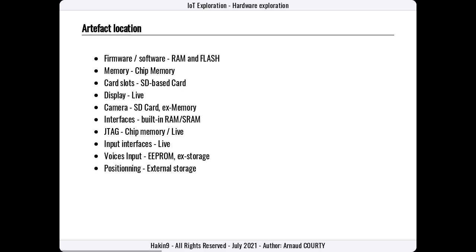From this methodology, these kinds of artifacts can be retrieved. Firstly, if you are finding firmware to do some reverse engineering, you should focus on harvesting in flash or in RAM, dump the firmware, mount all partitions on your system, and locate sensitive information like credentials.